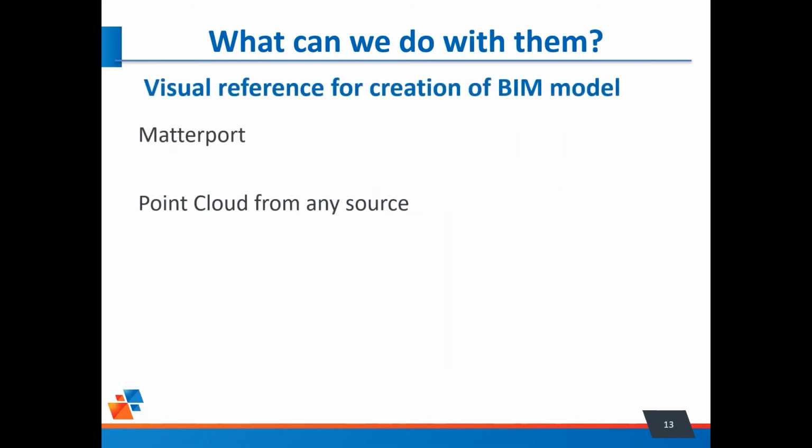Okay, what else can we use point clouds for? We can use them as a visual reference for creation of a BIM model. I already alluded to the fact that we can use that as a snapshot in time. But one of the big things that we do is use it more like a scan to BIM, and I'll talk a little bit about that later and show you a workflow of how we use it.